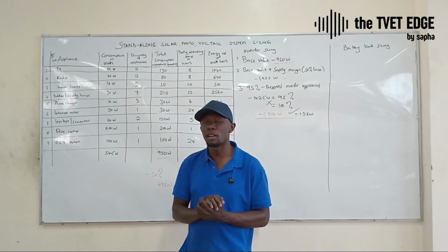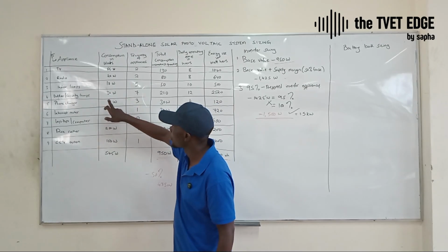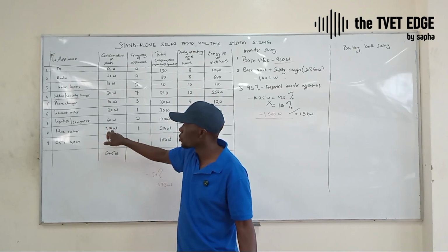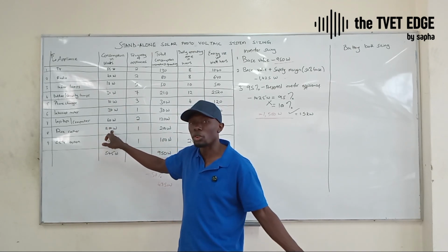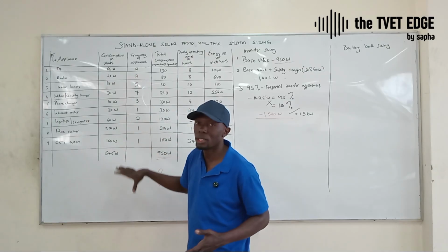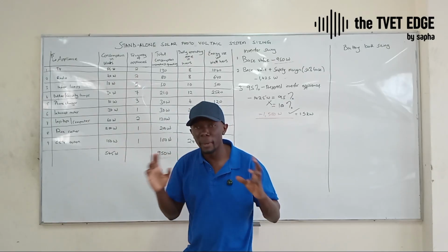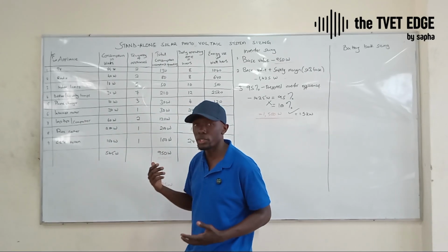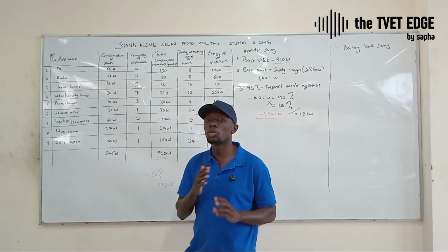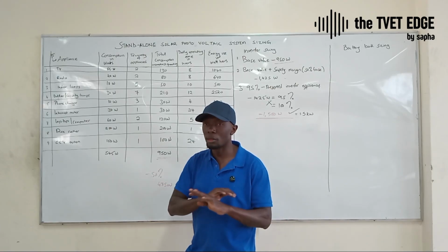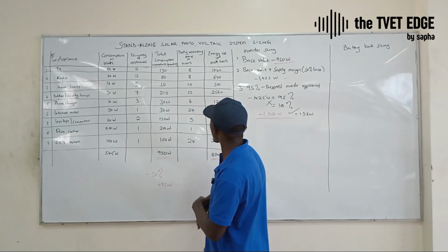For example, we can have a system with a load of probably 30 watts, but it's a capacitive load, and another load of 200 watts that's a resistive load. So how do we size this inverter to ensure that these components are catered for independently, not as a whole? Because for the standalone system, we are assuming this client is not going to load this inverter with ridiculous loads. They're just the basic essential loads.